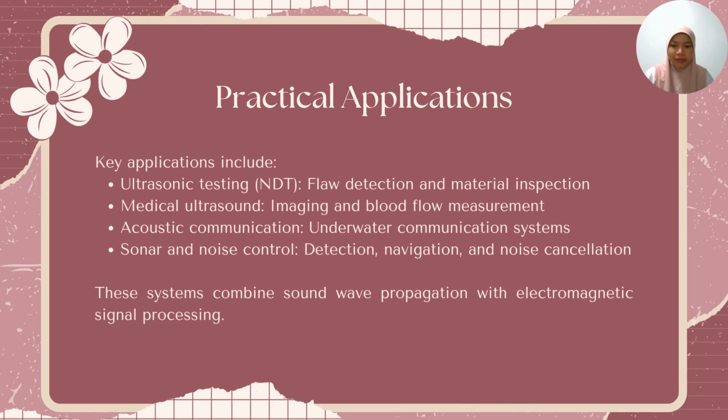Next are practical applications. This includes, the first one, ultrasonic testing for flaw detection and material inspection. A probe sends high frequency sound waves into a material. If there's a hidden crack, bubble, or weak spot inside, the sound wave will bounce back from that flaw. The second one is used in medical ultrasound imaging and blood flow measurement, where the probe sends sound waves into your body. Different tissues reflect the wave back at different speeds. The machine uses these echoes to build a real-time moving image.